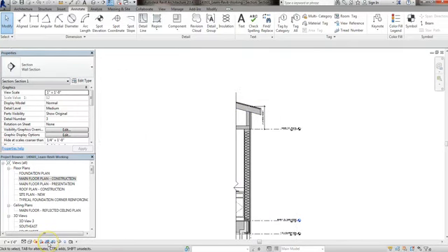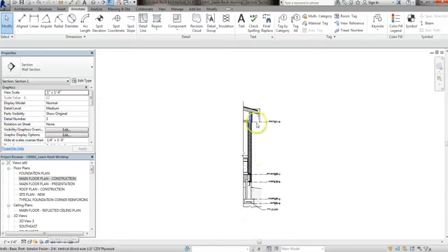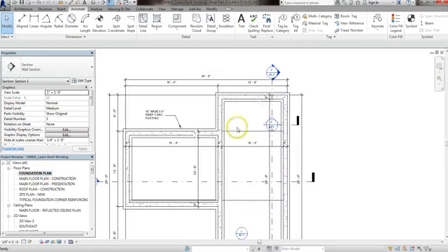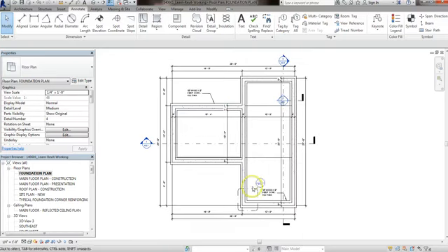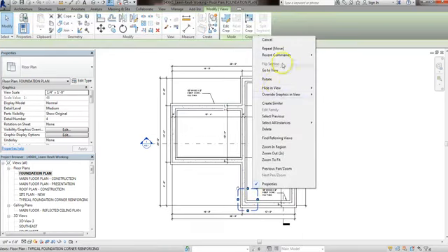Now that we have that, make sure, guys, to click down here so that you crop back your view, fill all of that out, and let's move to a detail of the foundation. We haven't been to the foundation much after we made that one pass. So, guys, remember to do all your dimensions around, do your dimensions in here. You can use your tag to call out this footer, and let's make this detail.